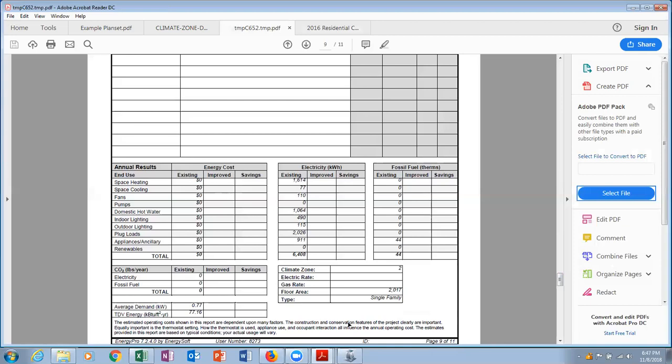Yeah. So let's say that in the energy model, if I had selected existing conditions, or I'm pretty sure I could do it now as a new construction model, then you select your alternative measures, and then it would start to calculate these. These aren't calculated in the Res Title 24 performance calculations. This is mostly filled out when you do just Res performance.